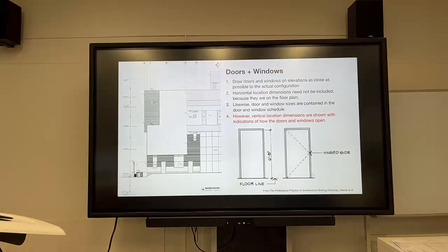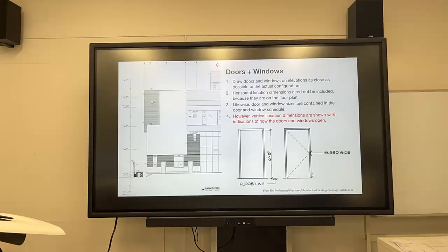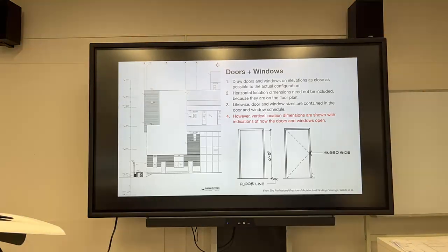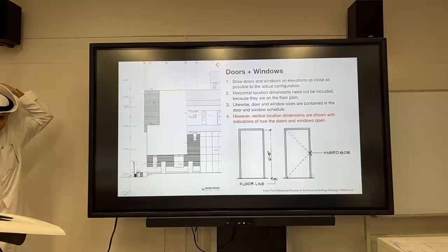Okay? Don't confuse it with going from here to the hinges. It starts where the hinges are. So I have the dashed line go this way and that way. So this door is going to be on the right side as well, and we take it to the corners. Okay. So always look for where the hinges are. That's where the center point is, and then you take it to the other two corners.